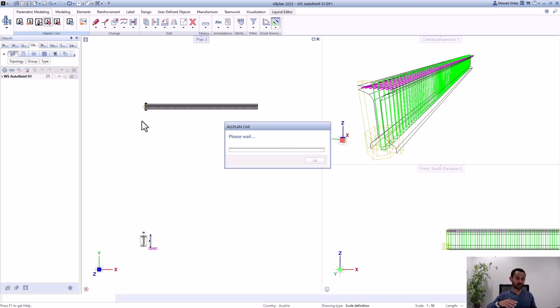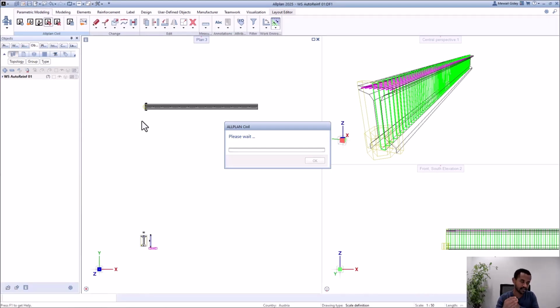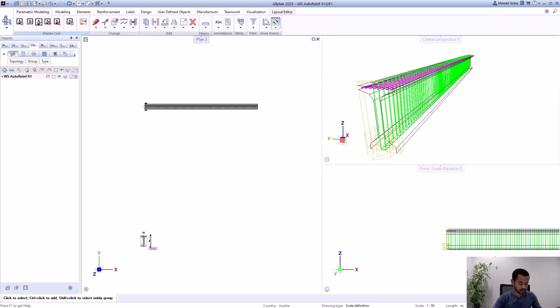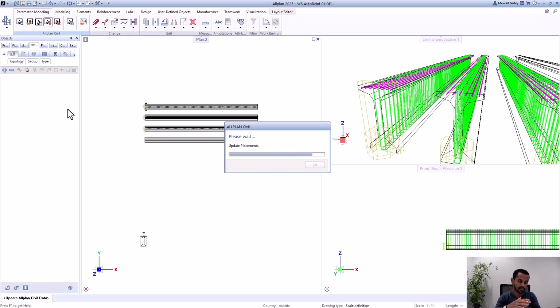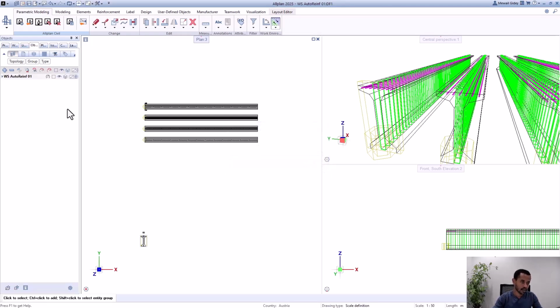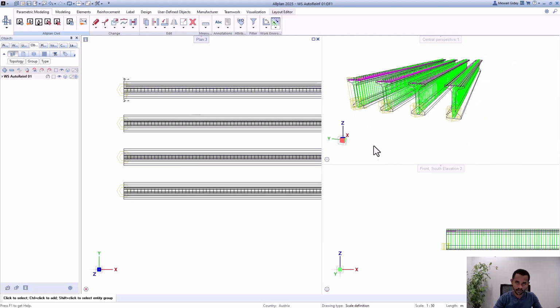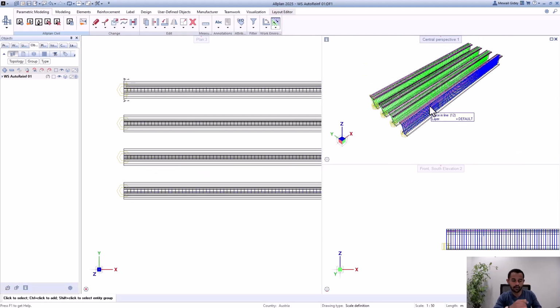And so the goal with this, what we want to see, is that we've only reinforced one structure, only the template one, but we want to see it in all the other structures as well, because they are all based on this template we have created for this link girder. And we would see that, okay, we imported all of them, and we want the reinforcement also to be placed for all of them as well. And you can see you have the reinforcement for all of them, for all the structure. This is just one small span and only has 4 members, but imagine if you have multiple spans and a lot of girders.